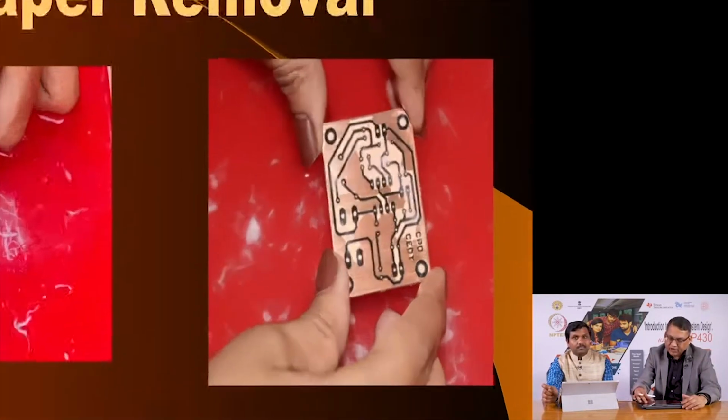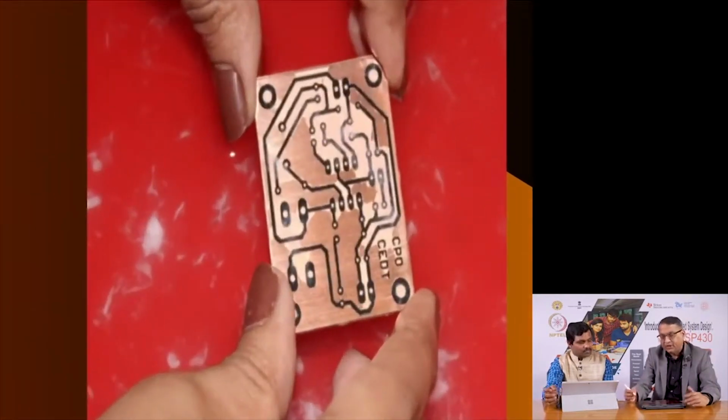And once you do that, this is what you will see. Now, you remember I mentioned that we need to print the mirror image of the layout, so that when we press, it automatically mirrors the mirror and we get the original. So, everything you see here is in the correct orientation that we want. It is readable English. On the layout it did not appear to be readable, and that is the test to see whether this is the correct print you have made or not.